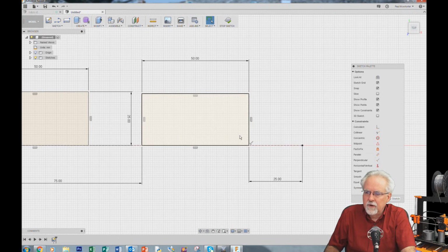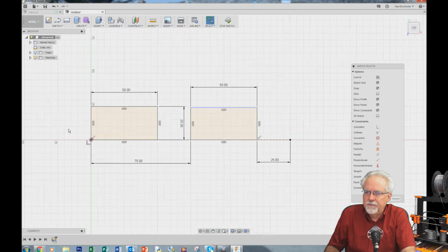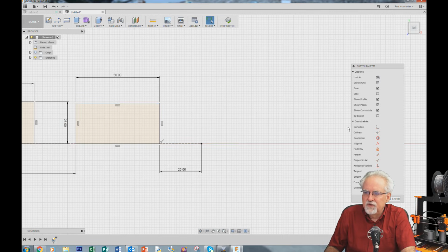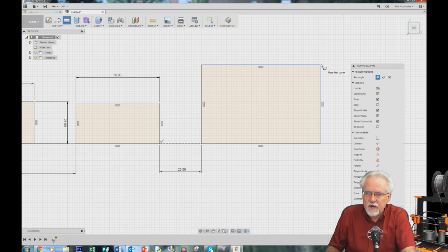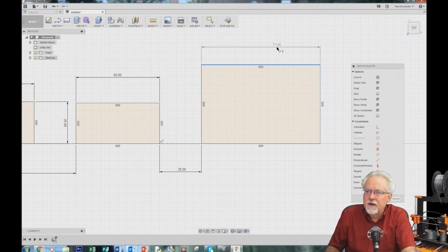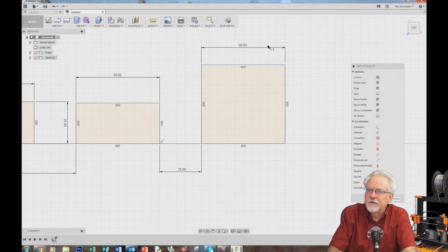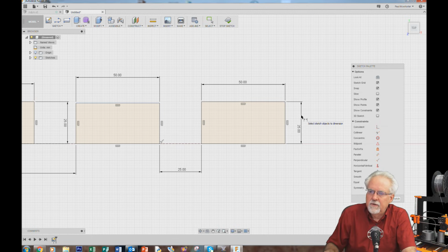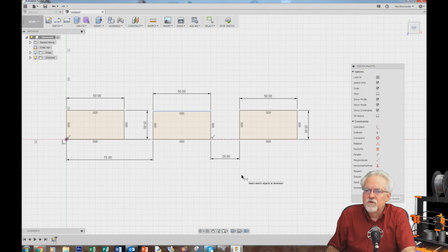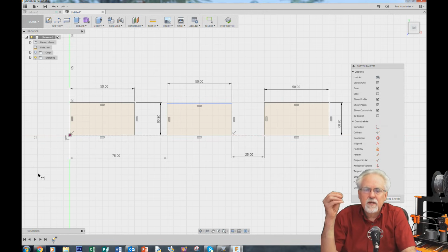All right, and now we are going to give ourselves room to draw here. So what do I want? R for rectangle. I'm going to click here. I'm going to come here. Now what do I do? D for dimension. I come here. How big do we want this? We want it 50. Enter. This, how big do we want it? We want it 25. Okay, so now we have drawn 3 rectangles.